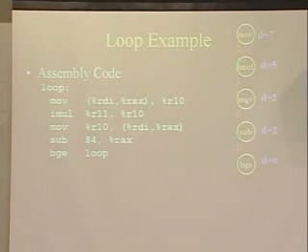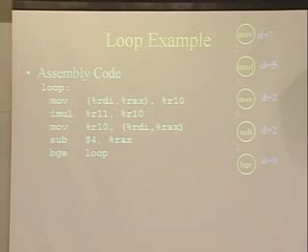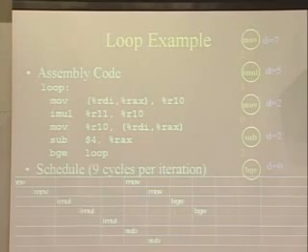At least they have to happen at the same time, because otherwise, with the other order, I would have updated it before I actually used it. So that's why I put a delay 0 in here. And then after the subtraction, you have to wait until it finishes to do the branch. Fair enough? Okay, so this is the loop.